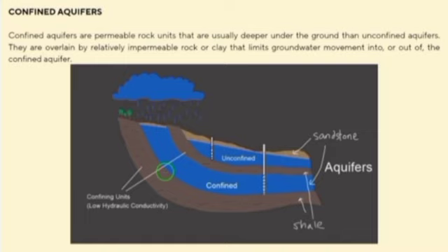Confined aquifer is located lower than unconfined aquifers, as you can see in the figure, and water is also stored there. The rock materials that cover confined aquifers, both up and down, are called shale, also shown in the figure. Because of this shale, water in a confined aquifer tends to rise up inside a drilled borehole because of the underground pressure experienced by the water.